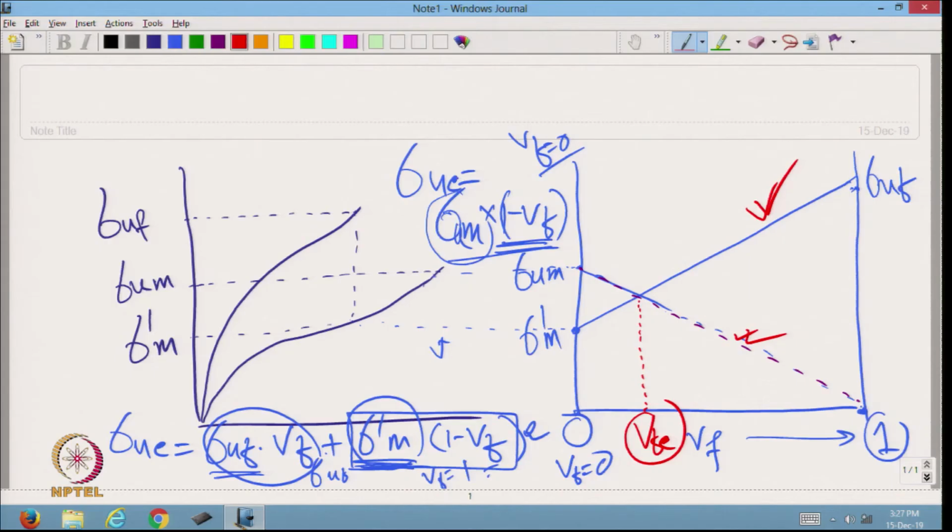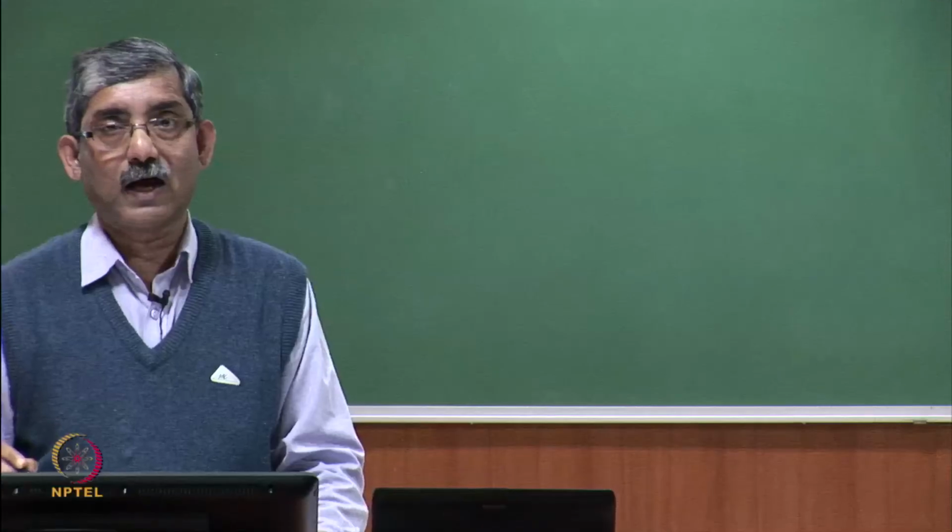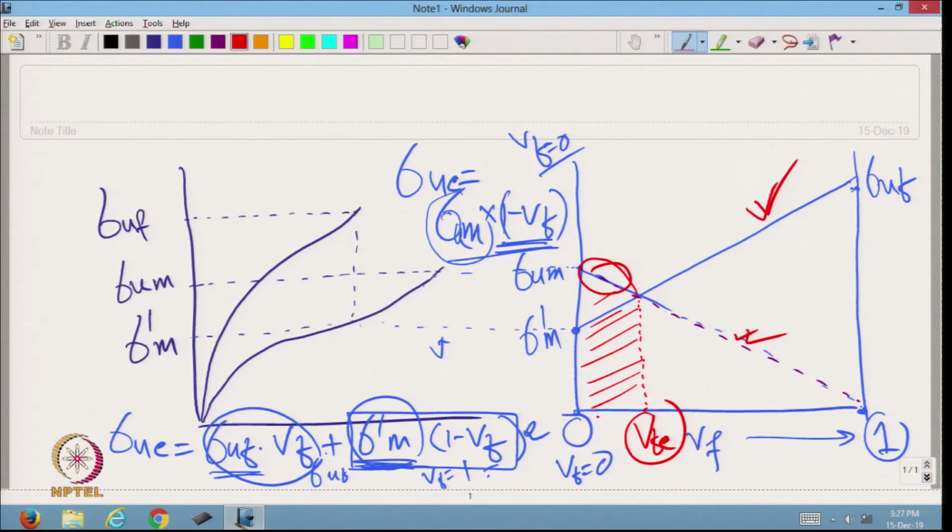So, at lower level, in this zone, the composite stress will be higher, because the stress of the composite at any point along the axis, at any level of volume fraction, will be the point where among these two equations, two curves, whichever is higher.